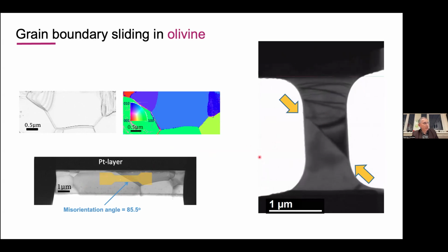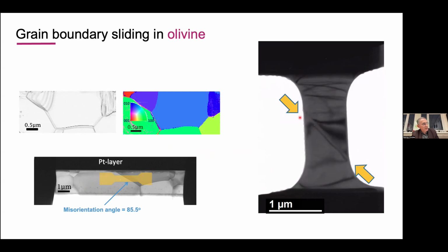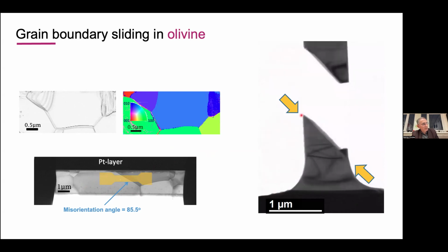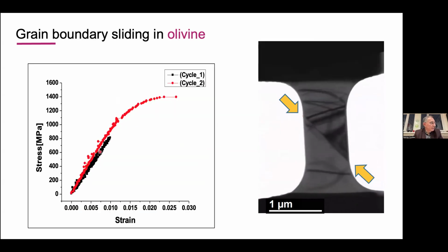So here you have the experiment which is running. You can see that you don't see anything, which means that there is no dislocations, nothing goes into the grain. We are still pulling on the specimen. At the end, you may see a tiny offset here, very, very small, nothing on the left, but here it moves a little bit and then bangs, it breaks. So it's not much, but still we can see that we did 2 cycles, one elastic going back, reversible, and then another one leaving the elastic regime and going into a plastic regime.